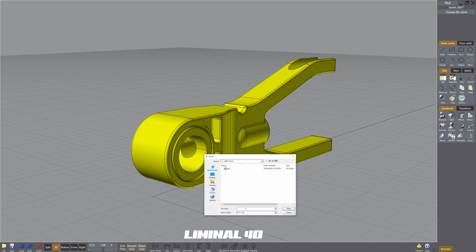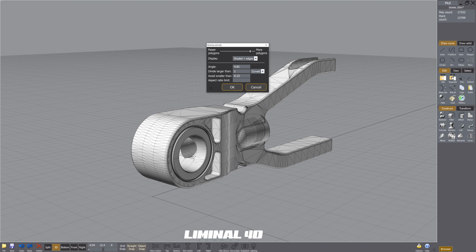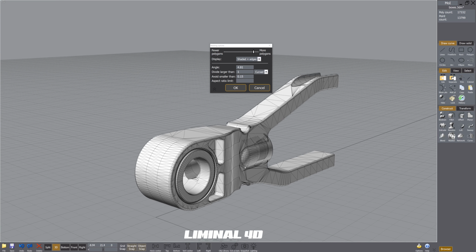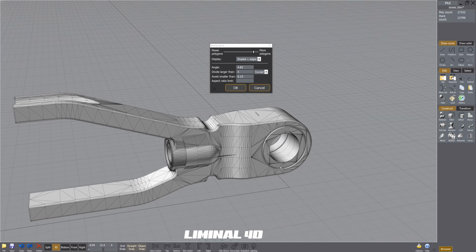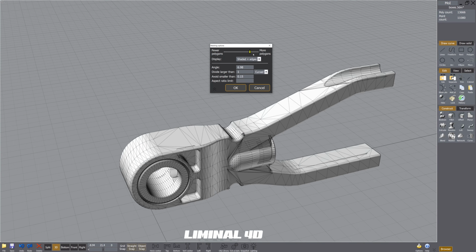.stl doesn't save texture information or color data. It's purely the geometry, often used for 3D printing. So we'll use that as an example. Give it a name, click Save. All right, now this Meshing Options dialog pops up, and here we go. If you notice the model changed, we get a live preview and you can spin around and look at all aspects of the model. Very handy.